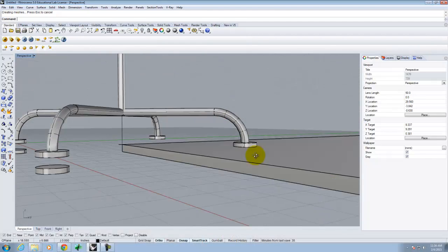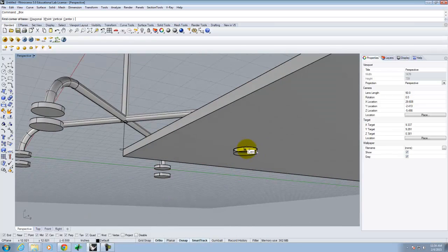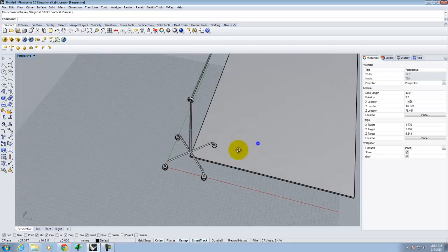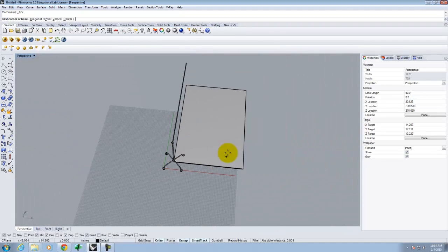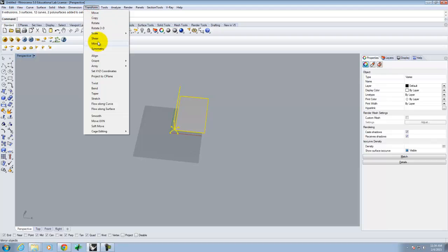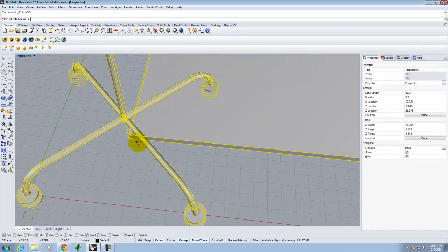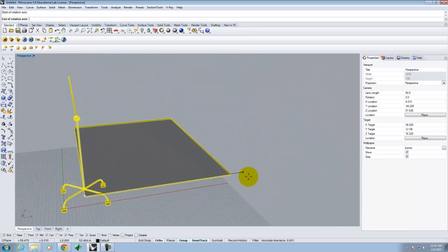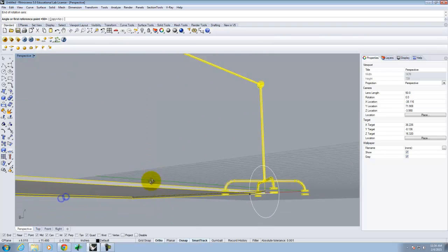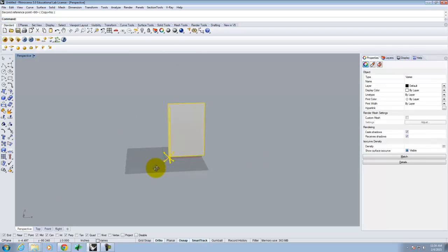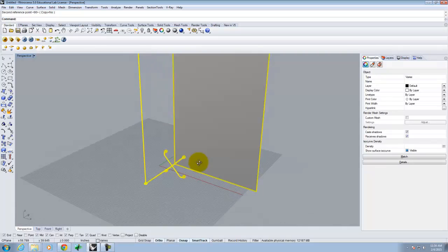Now, since I modeled it correctly, I have a little button on top and a little button on the back side, right? And the glass goes all the way through. Okay. Once I have this in position, I need to do one more rotate 3D. So let me take this whole object, and we'll go up to transform, rotate 3D. And I'm going to rotate along the surface of this glass right now. We're going to go from here to there is my rotation axis, and we'll fold the whole thing up so that it's a vertical surface and ultimately a vertical wall.